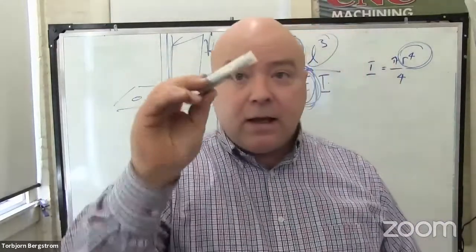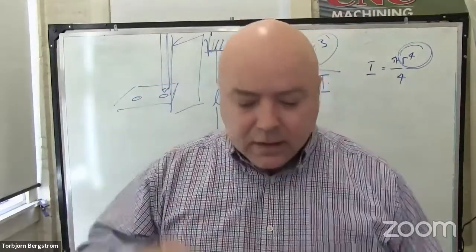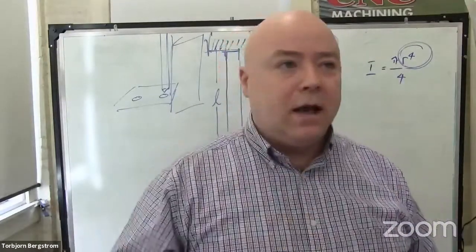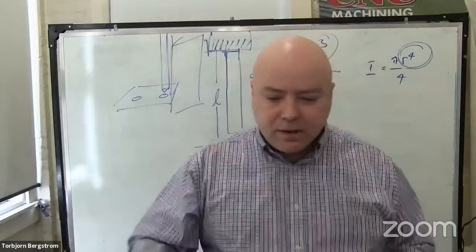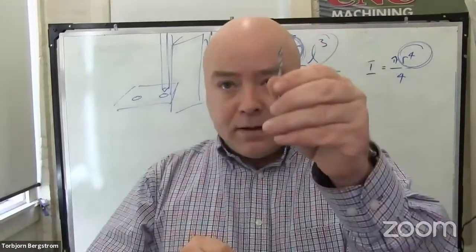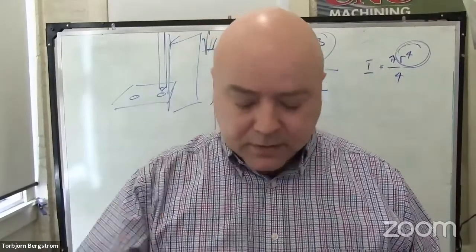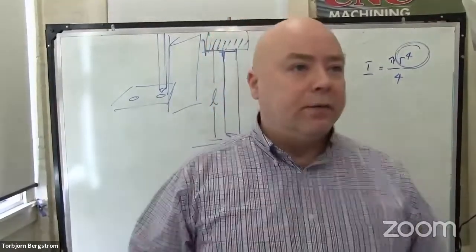We use a carbide drill like this in the cylinder operation to make that long hole that comes out the other side, because when we were using a drill like this to make that hole, they never came out in the center of the part, because the drill would always deflect and go a different direction inside there.